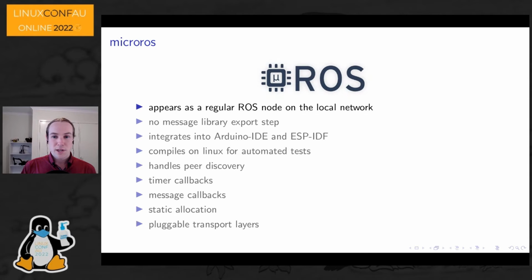Instead of wrapping some key functions in micro-side code and then leaning on the host for actual work, micro-ROS builds ROS 2 natively for the target microcontroller. micro-ROS provides a full-blown native ROS 2 interface for Arduino, ESP, and STM32. Because it uses mainline ROS 2 source, the developers were able to get incredible automated test coverage, which made for a really pleasant pull request experience on GitHub.